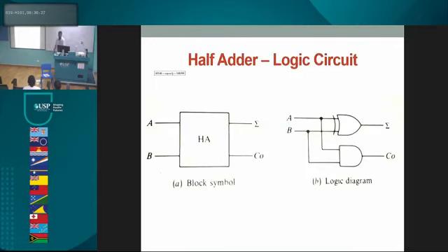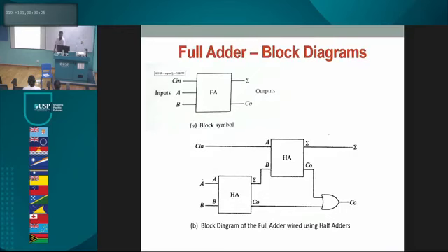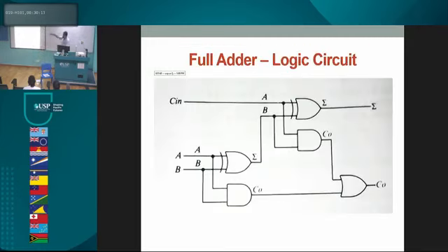How do you extend this system? So we do something like this. We put 2 half adders together in this particular way. The carry from here comes here, the carry from here comes here, and then you are fusing the 2 half adders together. This is important. Then this becomes our final circuit. But then again, this has got limitation. At every stage in time, you will have limitation. This can only add 2 bits. You've got a sum and you've got a carry, but it can do slightly more.